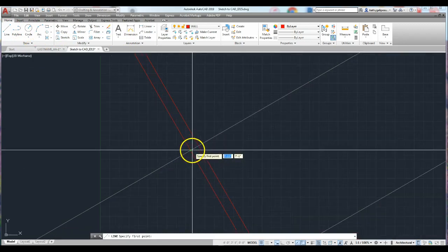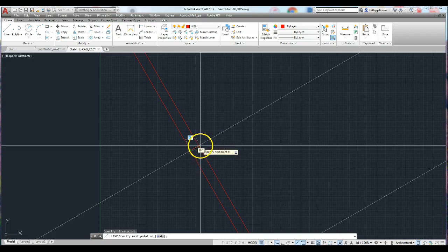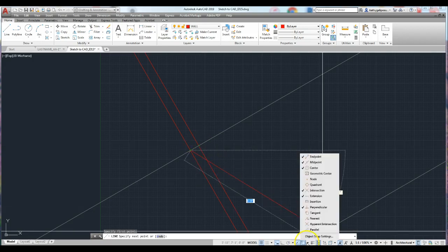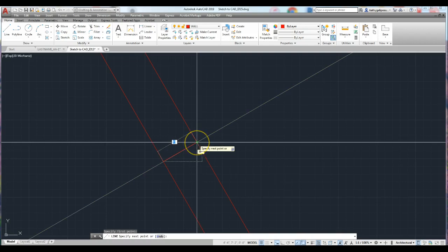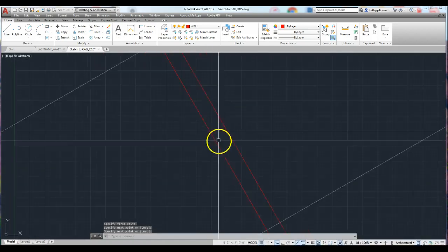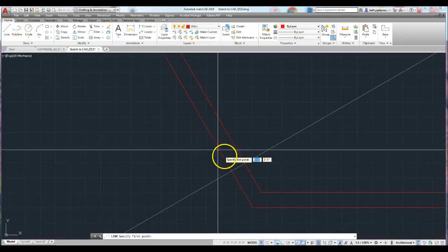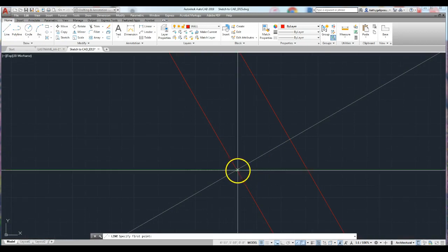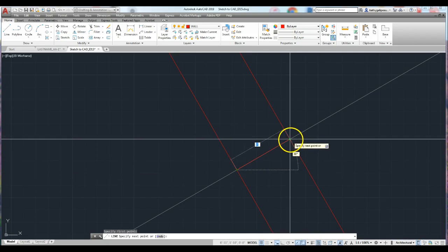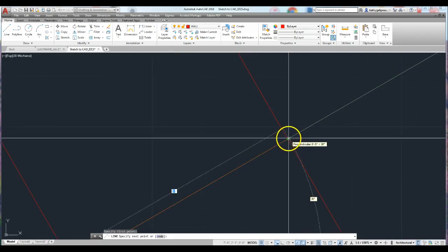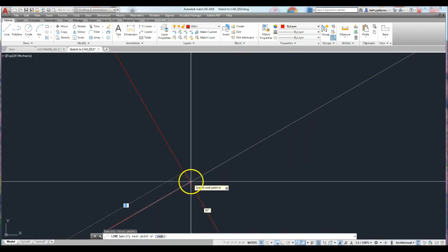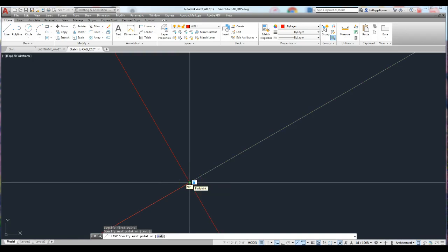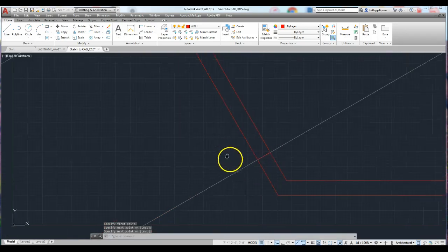So I will go back and switch back to my wall layer and draw a line snapping to the construction line that's crossing, and I can do an intersection. Let's make sure I have intersection selected. Yes. So intersection is going to look like that, simple. Intersection. And then I'm going to go down to this one. Again, draw a line where that is intersecting. Sorry, it's not really coming up super quickly here. Find the intersection. Okay. It said perpendicular, but it was the intersection also.